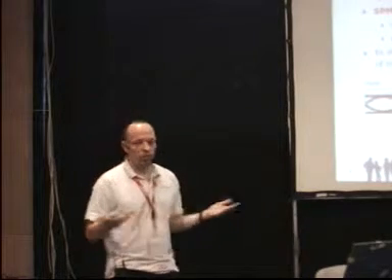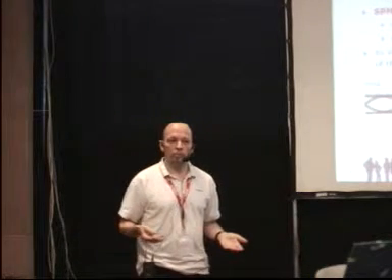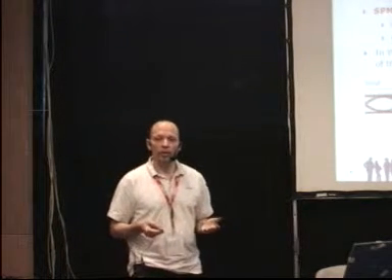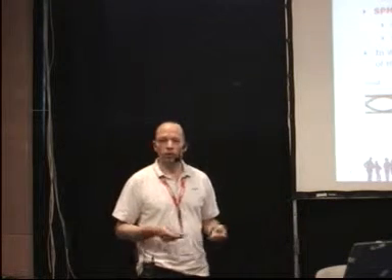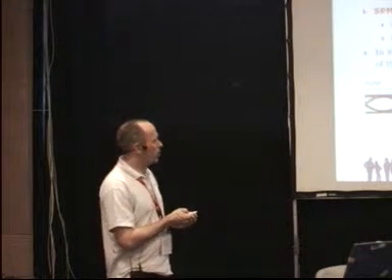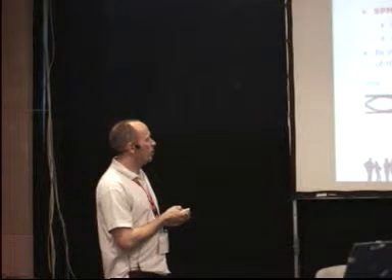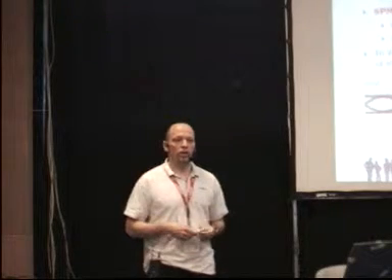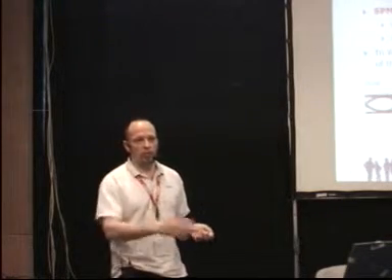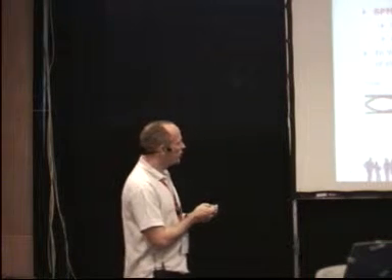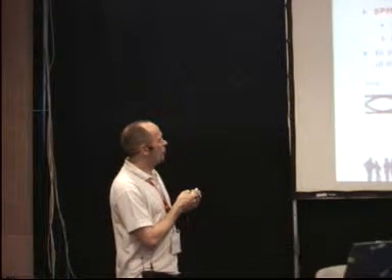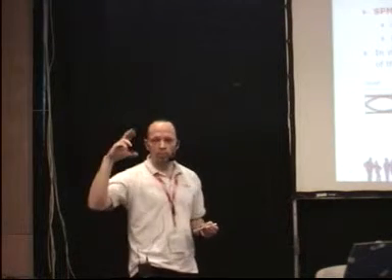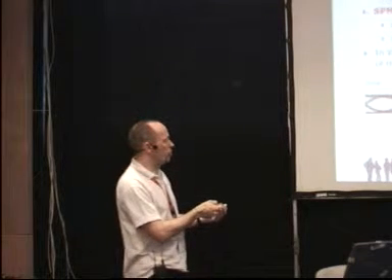Self-phase modulation simply interacts with chromatic dispersion, and this may be disastrous or maybe even useful, which is shown here. If we choose the right dispersion domain, the right sign of the dispersion parameter, so in effect the right fiber and the right wavelength, the combined effect of self-phase modulation and chromatic dispersion may be quite a good one. You can see it here, the eye opening increased rather than decreased, which is the case here.